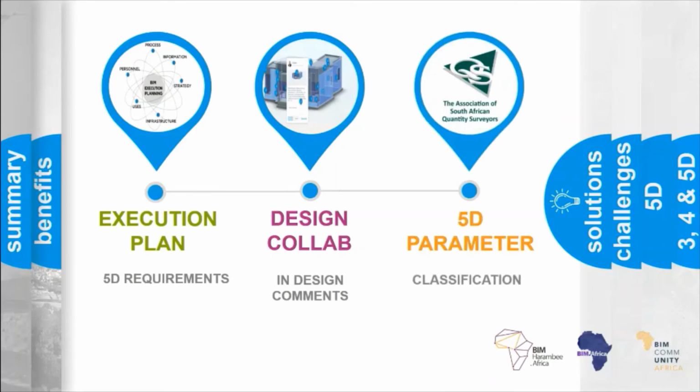And then, as said, the intention is to allow quantity surveyors access to the model to apply the 5D parameter. Quantity surveyors should be responsible for applying the 5D classification parameter themselves. So this avoids burdening the design team with this and ensures that the quantity surveyor takes responsibility for this classification and the integrity of the data that they apply to the model. And by applying a 5D classification parameter to each element or object in the model, the quantity surveyor is required to interact with each object, or at a minimum, each element type in the model. And during this process, quantity surveyors can provide comments in a live environment that the design team can review and respond to prior to the design becoming so advanced that significant abortive work is generated.